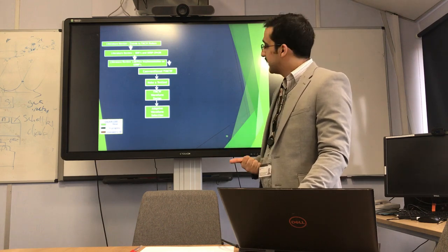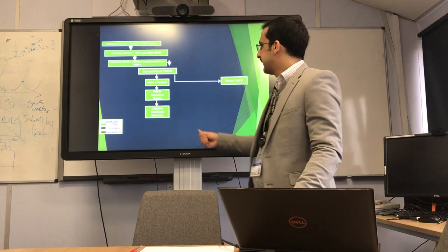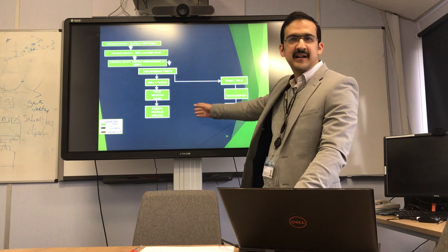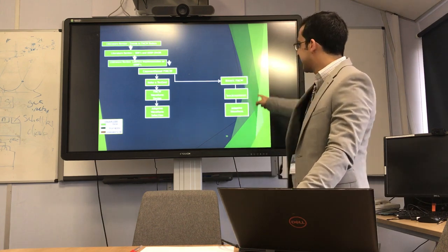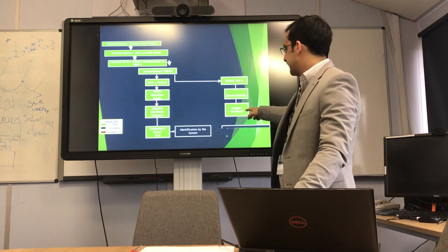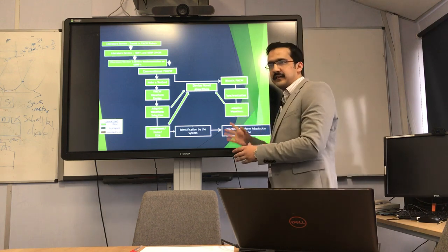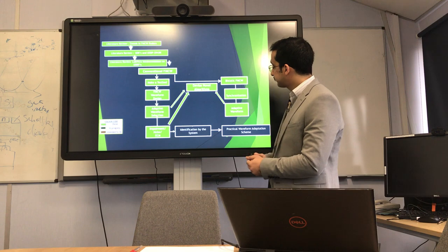I implemented conventional FMCW radar, made a testbed and FMCW waveform design. The waveform has been made adaptive by a very simple solution that you saw. Bistatic FMCW has been implemented, synchronization is being done, and the adaptive waveform part has also been incorporated by again a very simple solution.